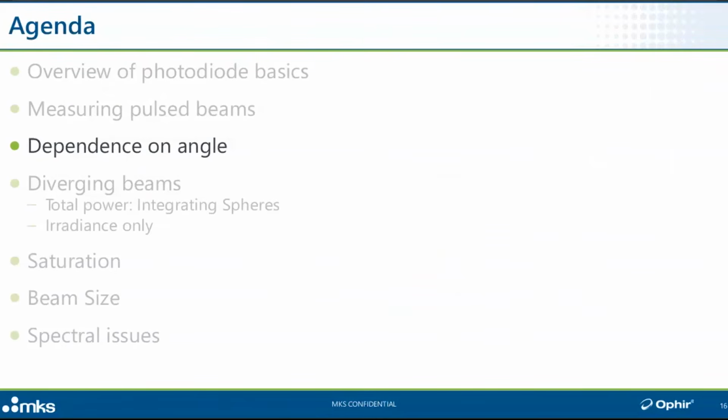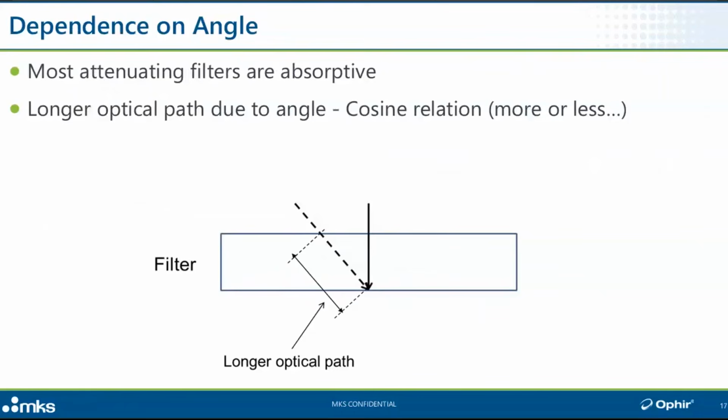All right, next item, angle dependence. This one's going to be a little bit more straightforward, I think. Semiconductor response depends obviously on the absorption of the beam. Absorbed light causes an electrical current to flow. It causes separation of charges, and then the electronics causes a current to flow. Okay, whatever. And the current is proportional to the power of the absorbed beam.